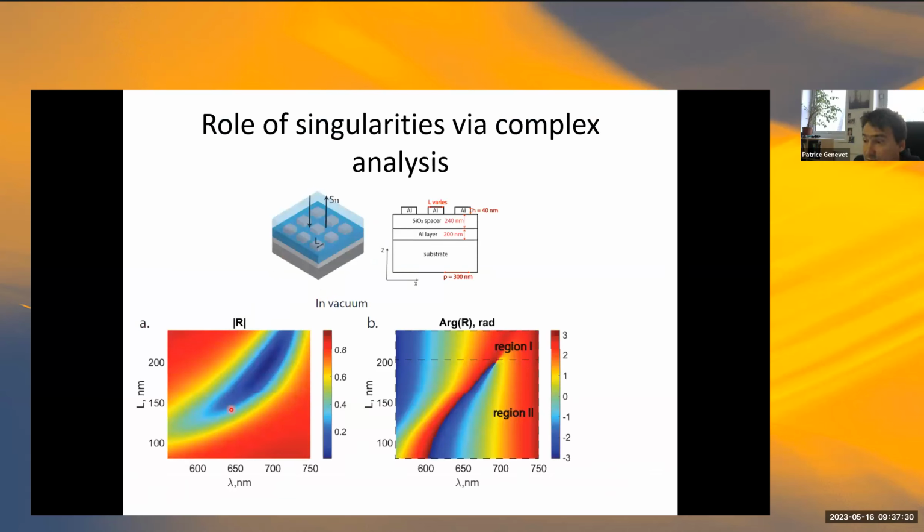And I show you here the same type of simulation, where I look only at real frequency excitation. I look at the reflection coefficient to measure this S11 coefficient on the metal dielectric metal structure, changing the real frequency excitation and the geometry, essentially as we did with the Fabry-Perot previously. And you see the appearance here of a 0, and at the position of this 0 in the parameter space, you again see a phase circulation. So when the imaginary part of the 0 is equal to 0, you are able to observe the 0 in the real frequency excitation.